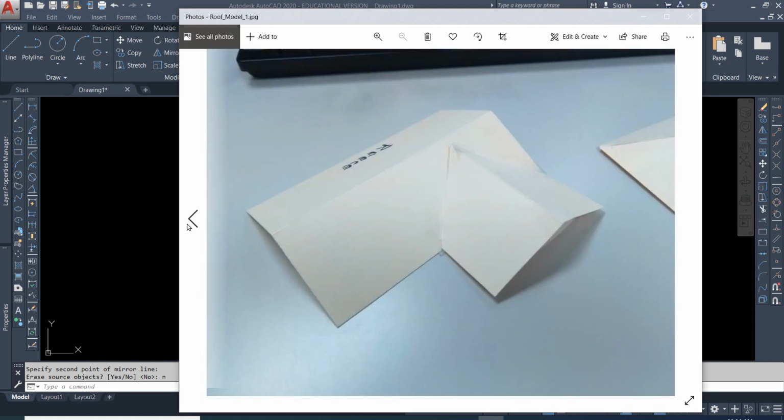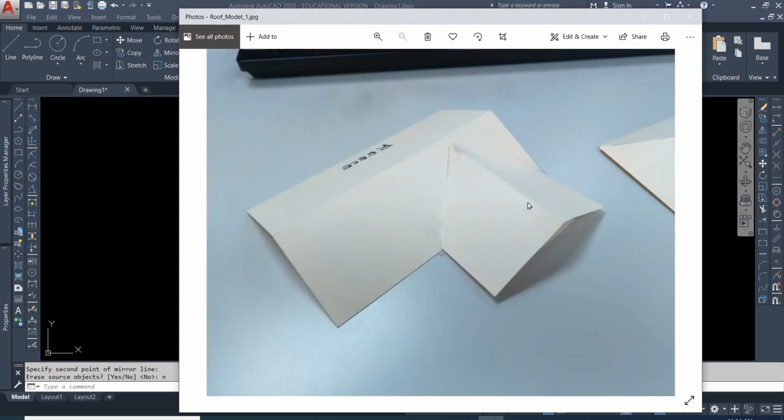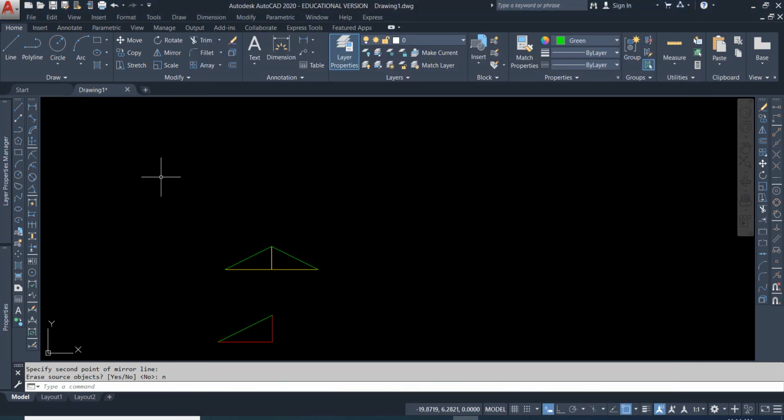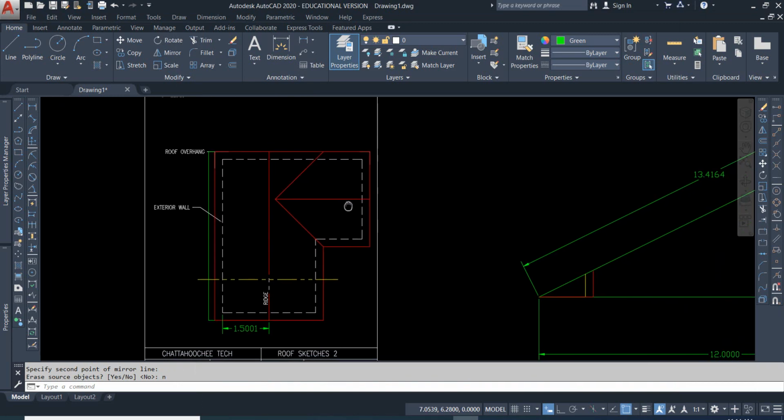Okay, now this part of the roof, if you notice, I made the main roof one piece, so it just goes straight through. And then the garage portion here, this little wing that steps off, is a separate piece that just gets glued on top of it. But you have to calculate a different slope distance because the span of this roof is different.